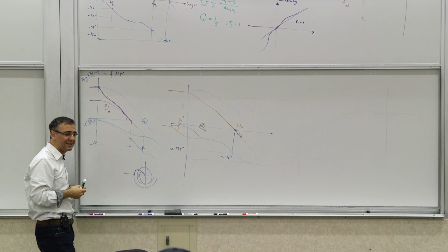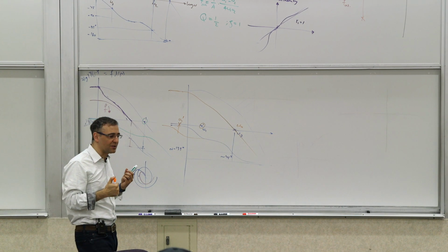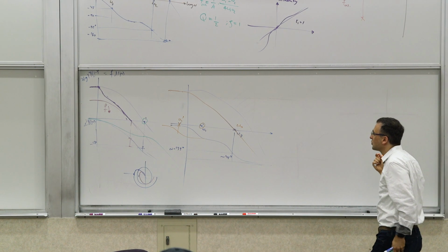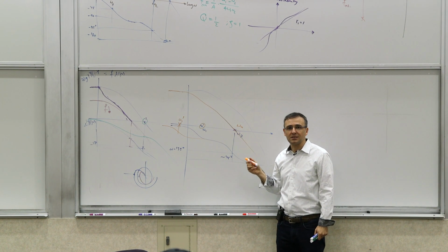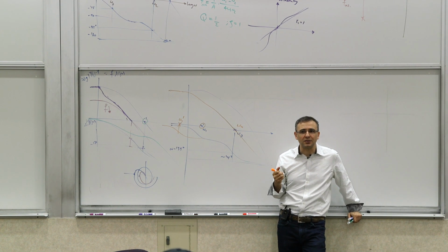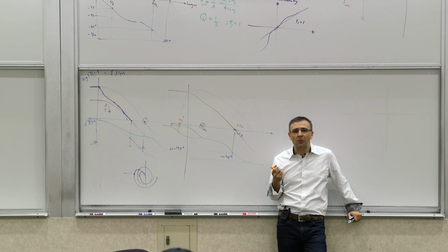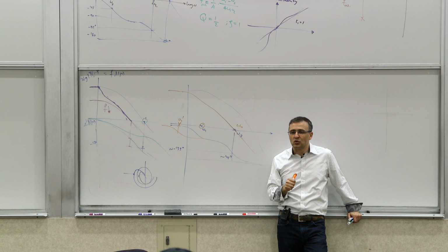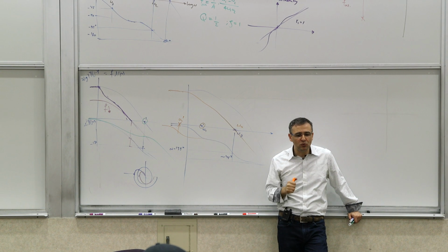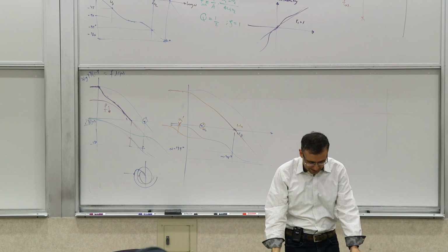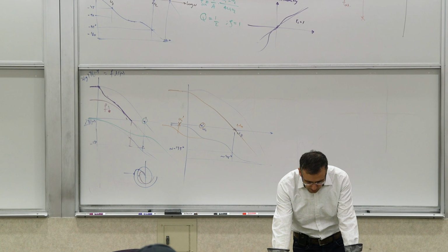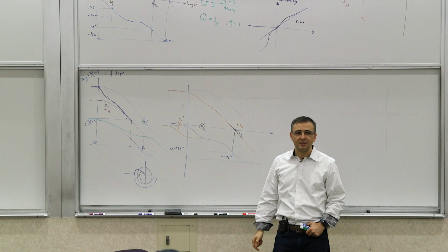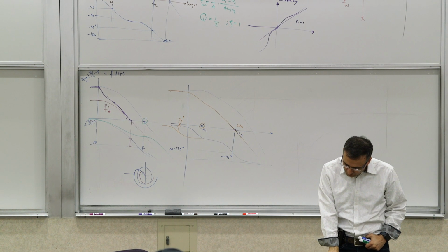So after this is done, now this is an important thing. You can see after the frequency stabilization of this sort is done, the unity gain frequency is really determined by, to first order, the first non-dominant pole. So it means that when you're designing an open loop system that you intend to use in feedback, you need to think about what your first non-dominant pole really is, because that's going to affect you.